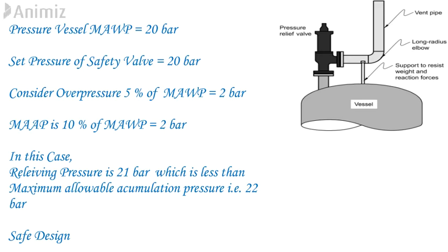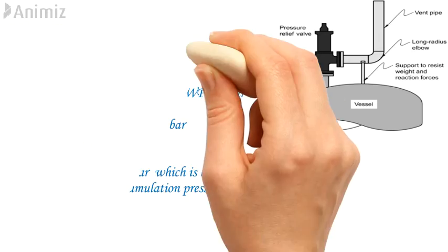Here, please make a note that it is not acceptable to increase MAWP in comparison with overpressure and raise the set pressure above the MAWP of the vessel in any case.